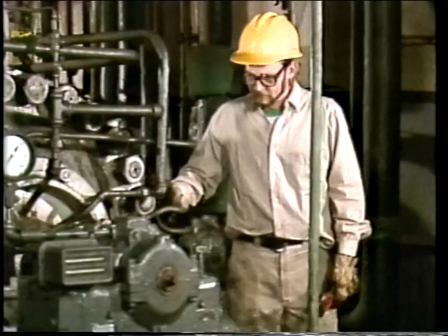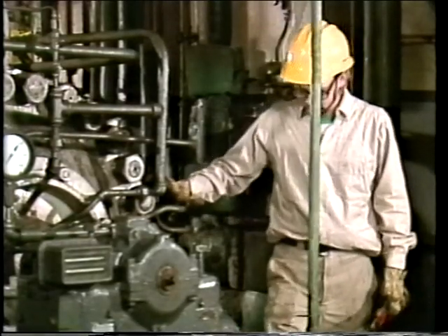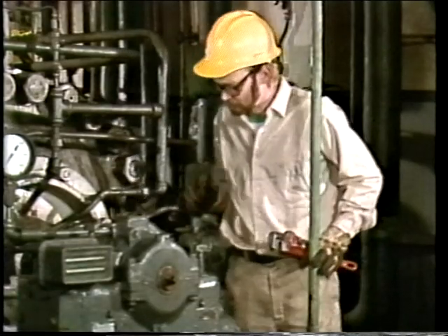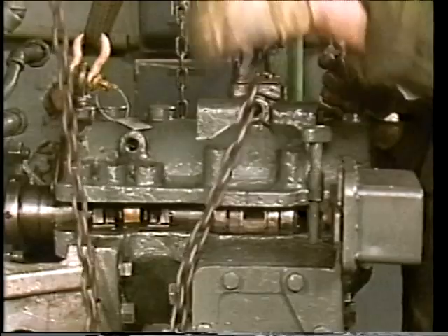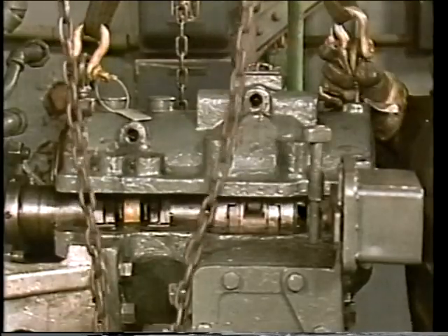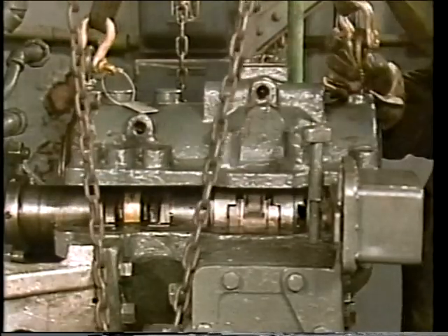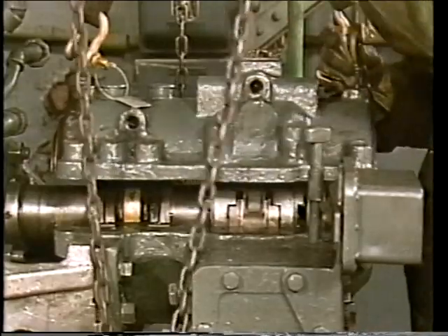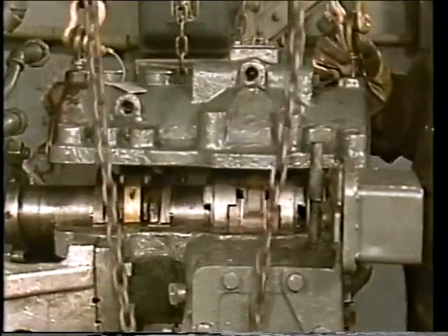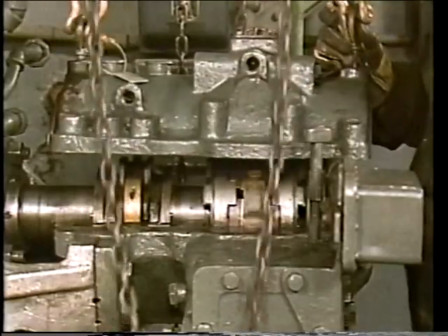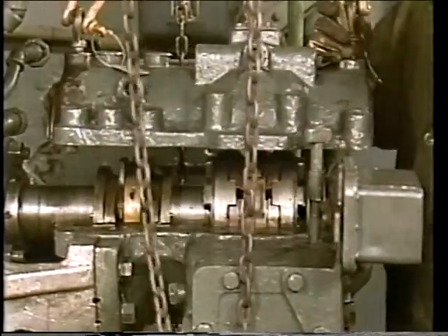Many vibrations can be traced to loose bolts or other parts. In most cases, these parts simply need to be tightened or replaced. Damaged or worn bearings can also cause vibration in rotating equipment by not allowing the shaft to rotate properly. Both sleeve-type bearings and rolling contact bearings produce distinct vibration frequencies as they wear or fail.